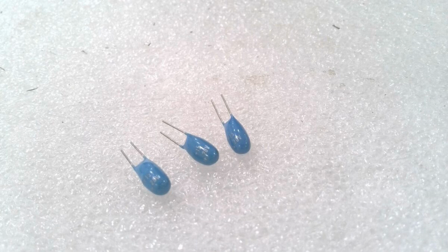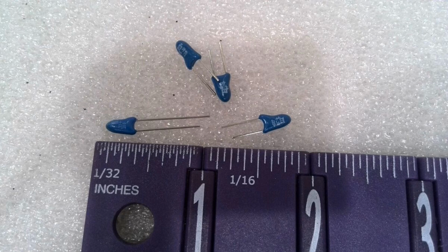4. Additional layers. Carbon layer. On top of the manganese dioxide or polymer layer, a thin layer of carbon is applied. This acts as an intermediate conductor between the cathode material and the external termination lead. Silver layer. To further improve conductivity, a layer of silver paste is applied over the carbon layer. This silver layer connects the capacitor to the external leads.